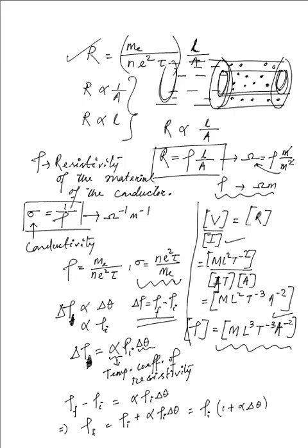As you can see from here, alpha is simply equal to the change in resistivity per unit resistivity per unit degree rise in temperature, in terms of Celsius scale or even Kelvin scale. Now obviously, because you have resistivity at the top and resistivity at the bottom, they will just cancel out, so the unit is simply Kelvin inverse or a degree Celsius inverse. And likewise you have the dimension as well to be equal to Kelvin inverse, K inverse. So that is the temperature coefficient of resistivity.